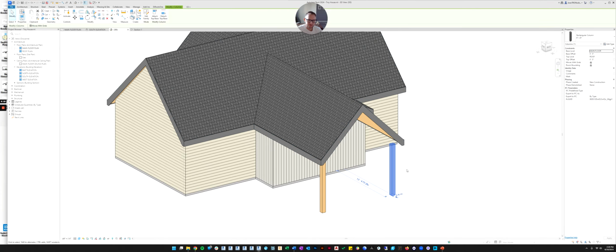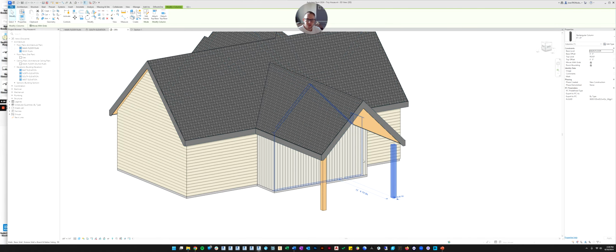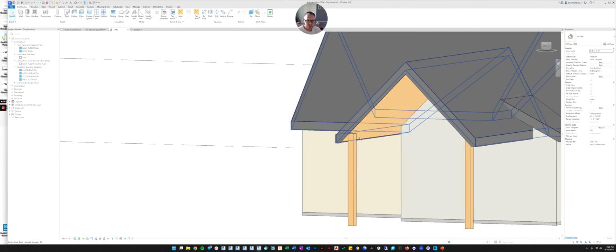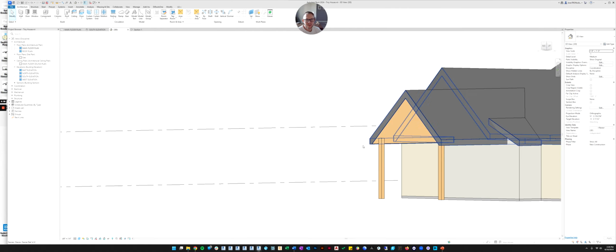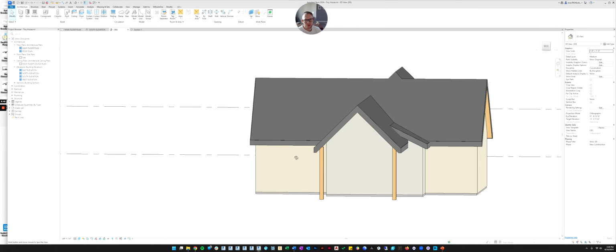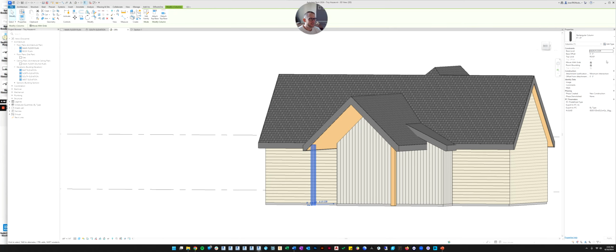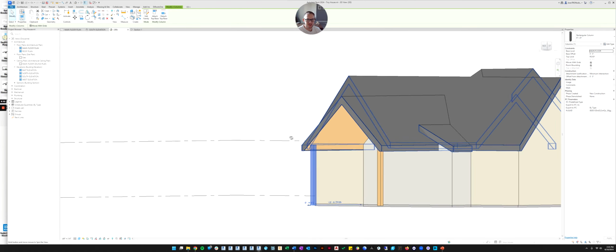So let's probably keep this at the roof level, but I think we can attach the columns. If you click these two columns, they are similar to walls, so you can hit the attach button up here on the modify tab, and we can attach them to the roof, and they'll go up to the roof. They are a little funny in how they join. That's probably as good as you're going to get as far as a joint. The only way to make it look better is to manually set the top level and push it up into the roof so that it's hidden inside the roof.